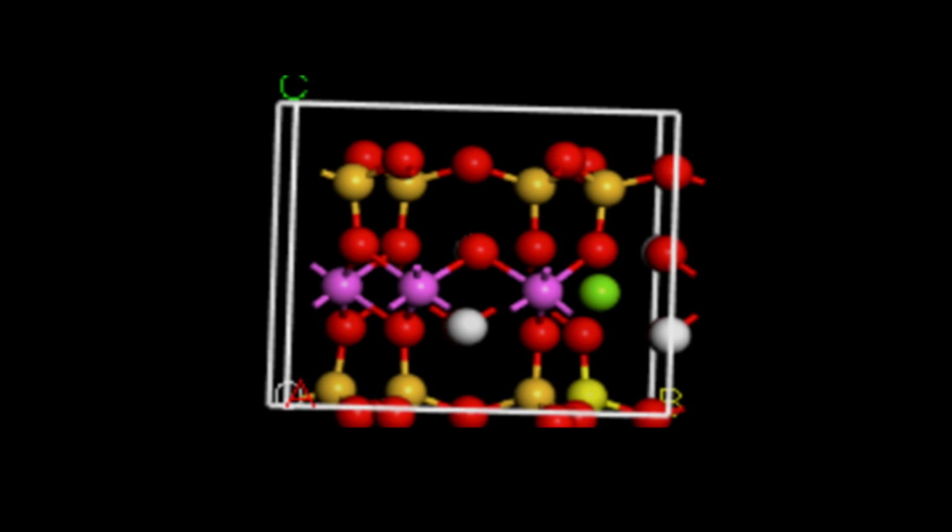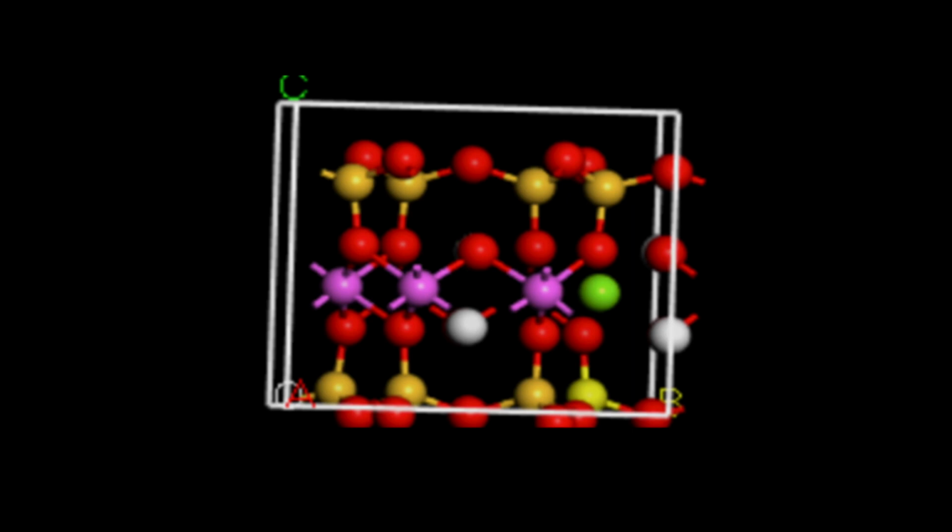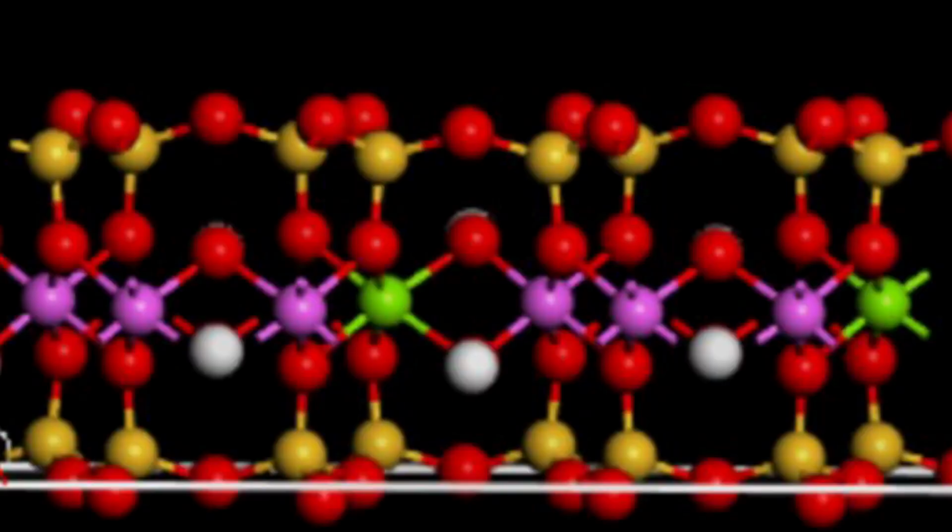The unit cell was then geometry optimized using the DMOL3 module in Material Studio and GGA PBE functional. This process is important as optimized structures often correspond to how a substance occurs in nature. Once optimized, proper charges were assigned to each atom, using the ClayFF force field data, which is a general force field used for the simulation of hydrated and multi-component mineral systems. This unit cell is then replicated to create a 1x2x1 supercell that will be used in production simulations.